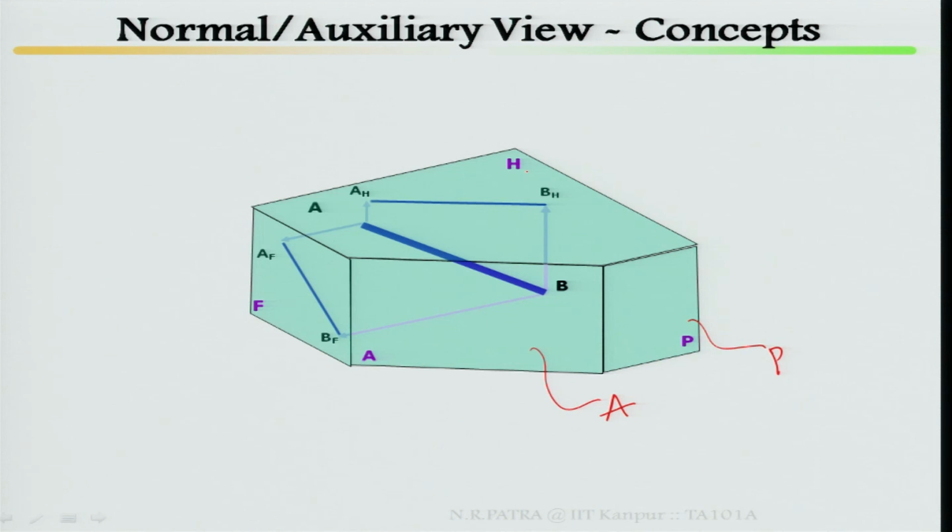Measure the distance from the hinge line, from here to here, from here to here, same hinge line; the distance has to be located from here. Now, look at this animation, project it back, this distance, project it back, this distance. So this is your true length, TL.